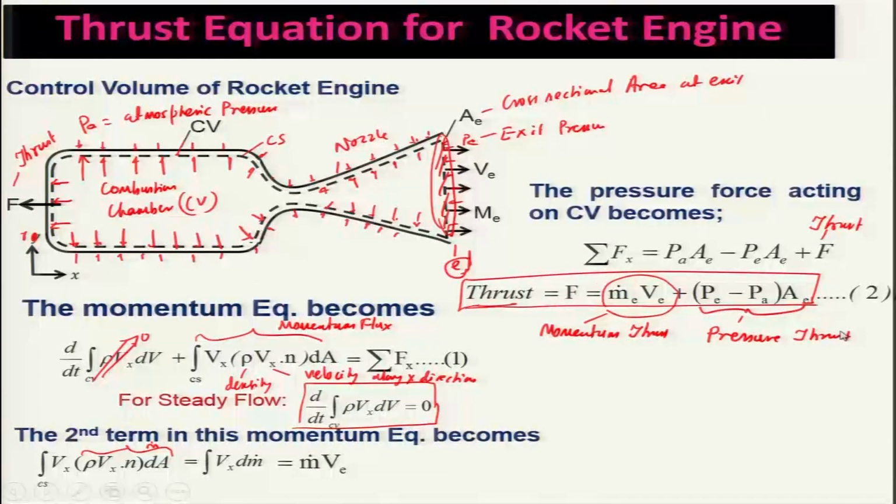There will be pressure change in that. So, as a result, you can see that the thrust is independent of the flight velocity, because the flight velocity is not coming in this expression. And sometimes, of course, we need to look at which term is important, and as the altitude is changing, this P A will be changing along altitude. So, therefore, this pressure term will also be varying.